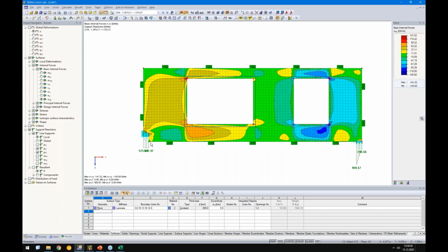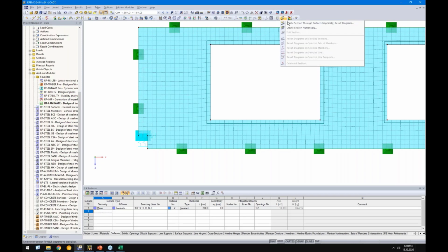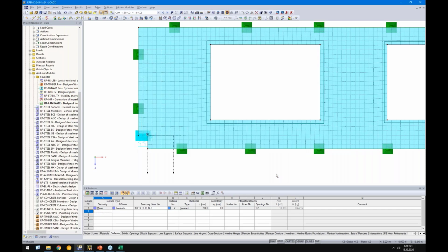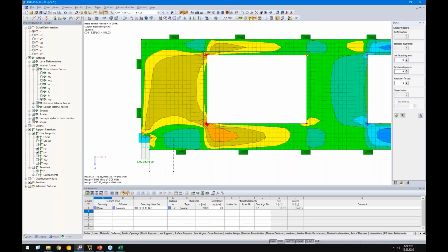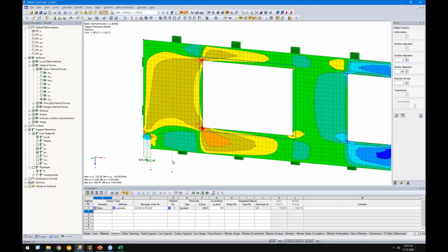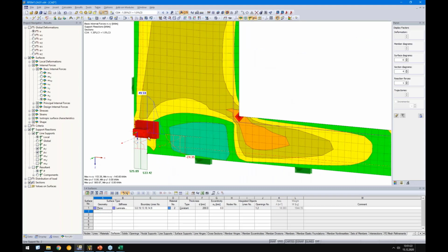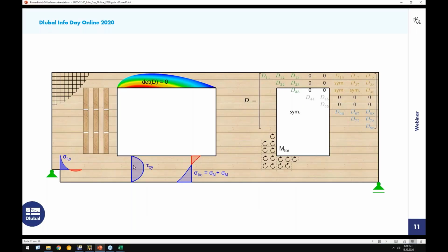Okay, so then let's check here this notch result, and in this example I will create a simple section. The section should start here and should go to 5.5 meter for surface number 1 in, let's say, -c direction. Of course, the section must go out of the plane, and then you see exactly here this stress. Maybe better, in this case I used NY. So maybe better to use a finer FE mesh here, and then you get this typical transversal tension curve, which is shown here.